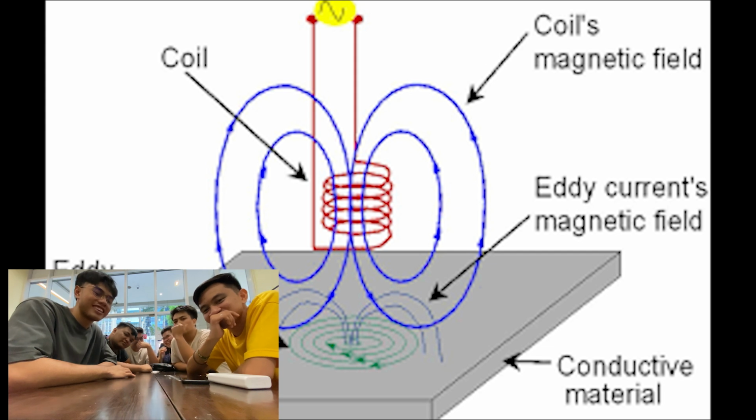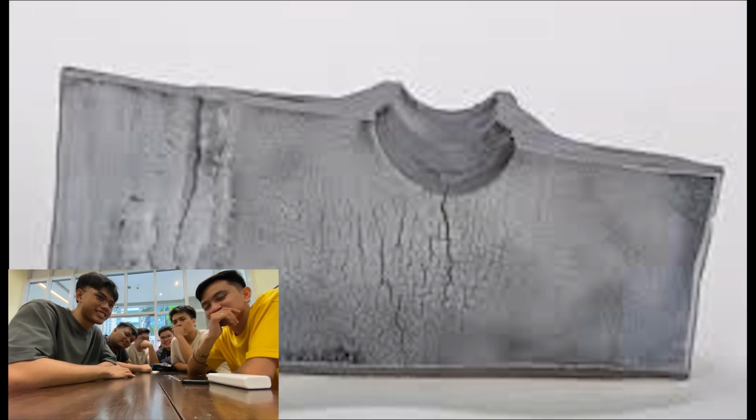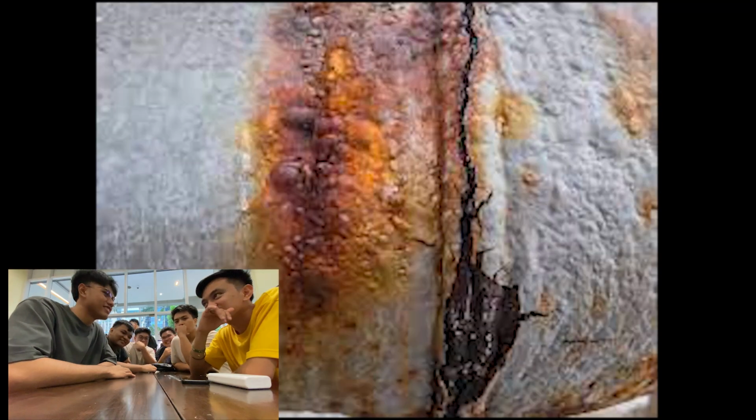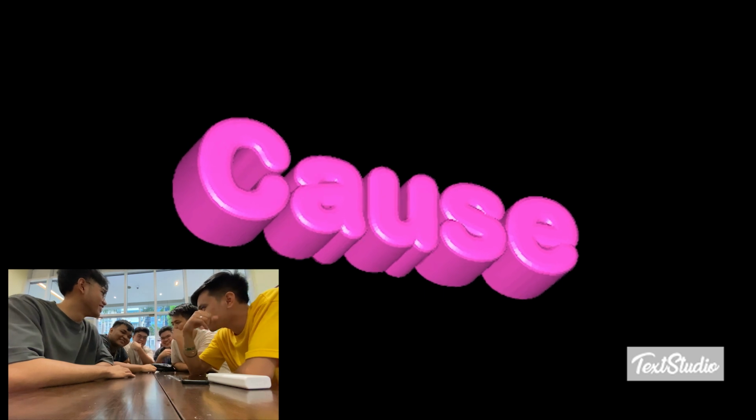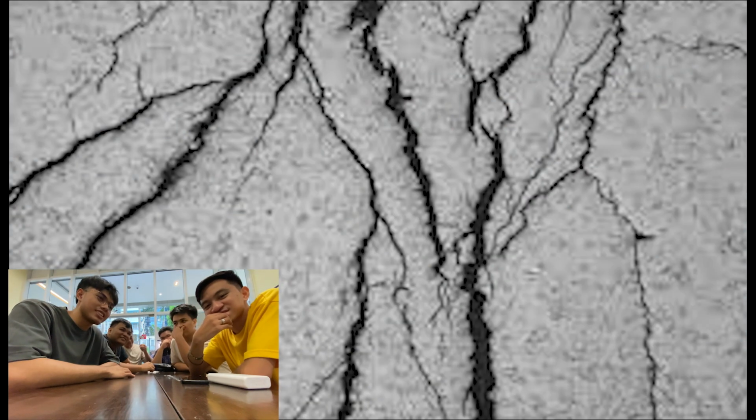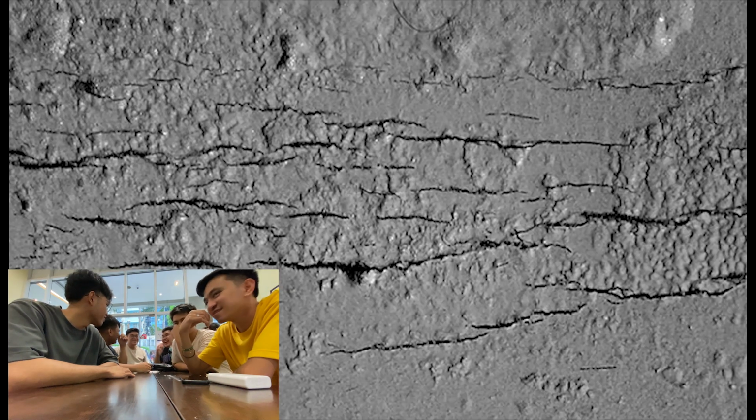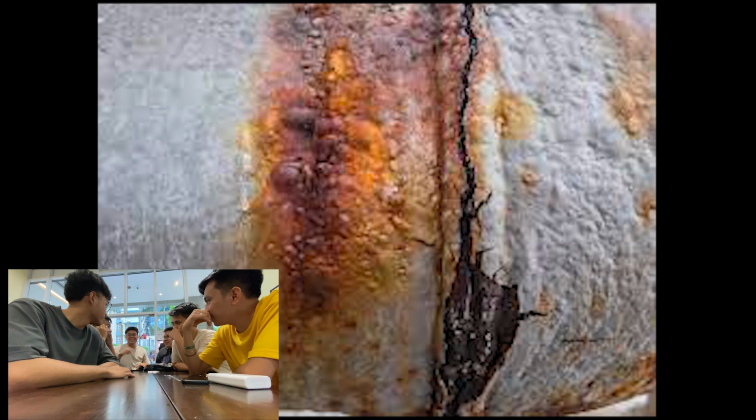Ninth, stress corrosion. This form of corrosion is particularly dangerous because it may not occur under a particular set of conditions until there is an applied stress. Cause: stress corrosion occurs when a material exists in a relatively inert environment but corrodes due to an applied stress. The stress may be externally applied or residual.